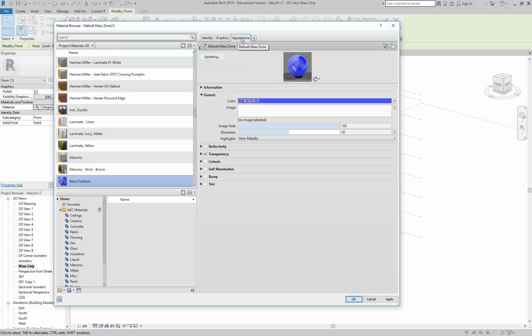Lovely. And then don't forget, it's a good reminder, keep an eye out for the sharing notification. When you see a number over the hand, that's a bad thing. It's the worst decision they ever made with Revit to let you do that. And so when you see materials changing and you don't expect it, it's usually because you haven't taken care of that. Whenever you duplicate a material on the list on the left, it doesn't duplicate the appearance. It keeps it linked to the original. So duplicate the appearance too, just out of habit, and that avoids that problem.